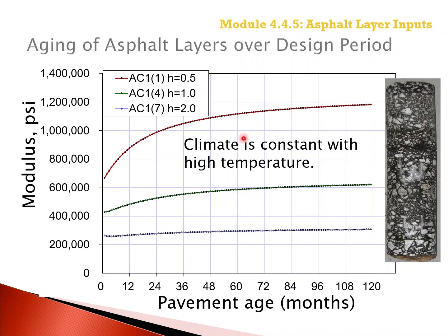The aging model used in the PMED software is called the Witczak-Mirza aging model. It uses binder and volumetric properties of the materials in the aging predictions. The key point is that different asphalts age differently, and you need to consider differences for a particular application.